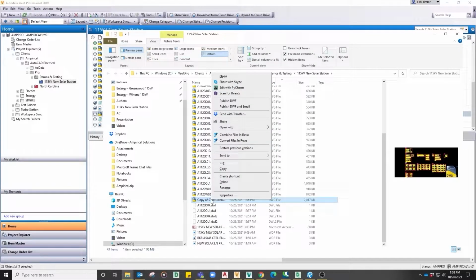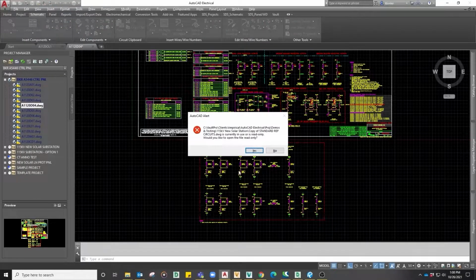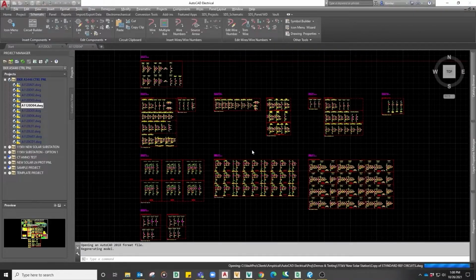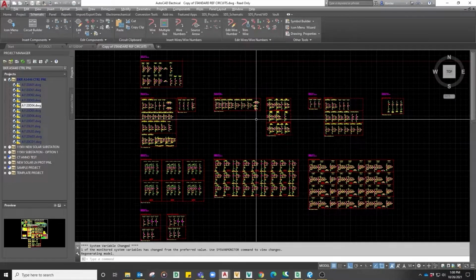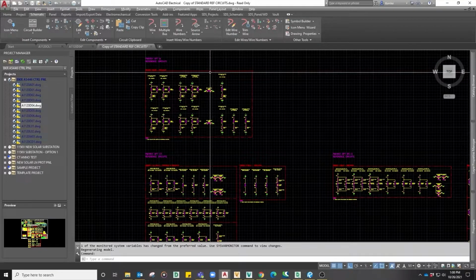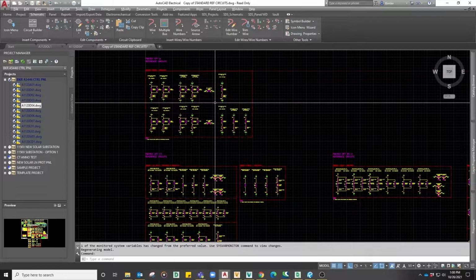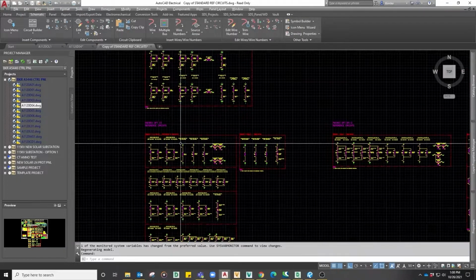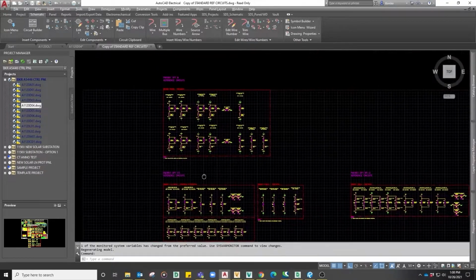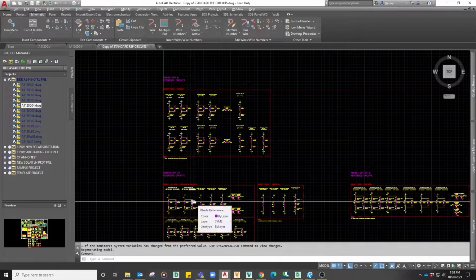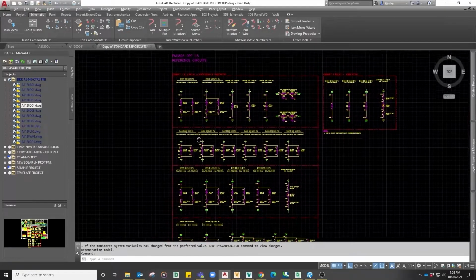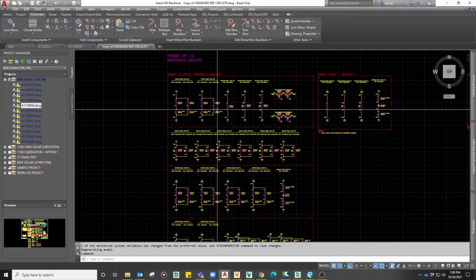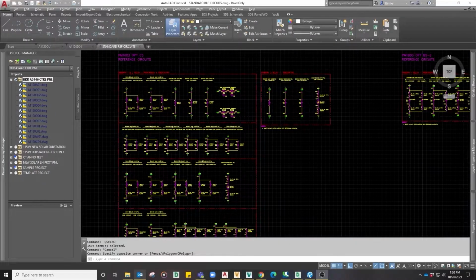There it is. The reference-only versions in this drawing are grouped by the standard from which they came. So in this example, user 1 is working on the breaker control panel. So I'll find the reference-only protection outputs coming from every panel except for the breaker control panel. And in this example, we're working from the line protection panel standard. It's located right here. At this point, user 1 can begin copying and pasting reference circuits into the drawings based on the engineering markups.